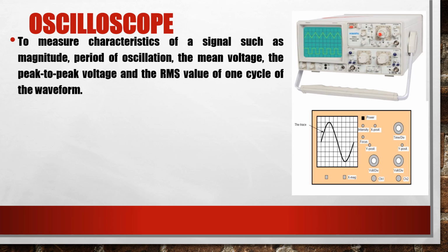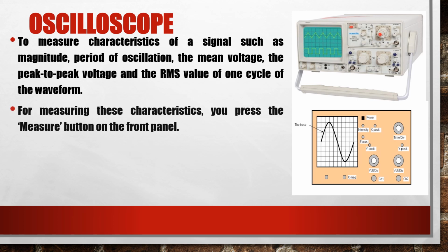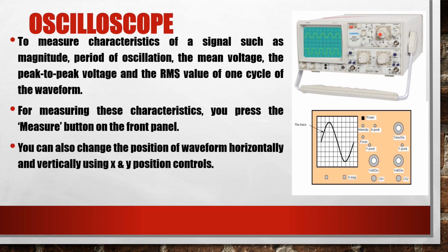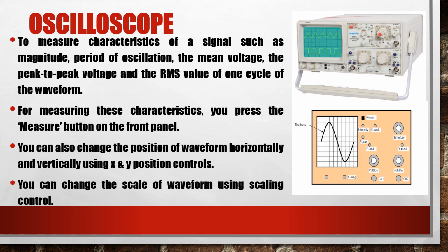For measuring these characteristics, you press the measure button on the front panel. You can also change the position of waveform horizontally and vertically using X and Y position controls. You can also change the scale of waveform using scaling control.